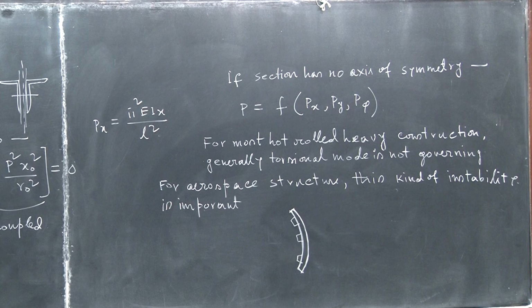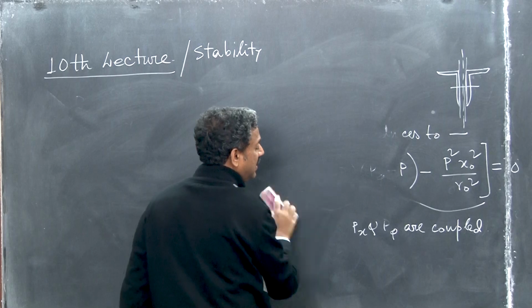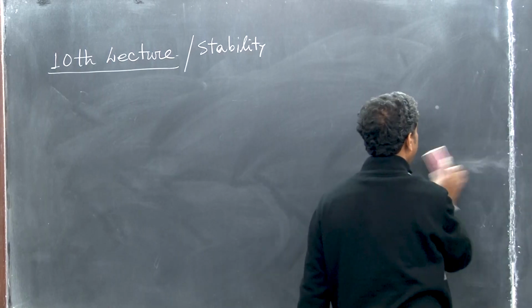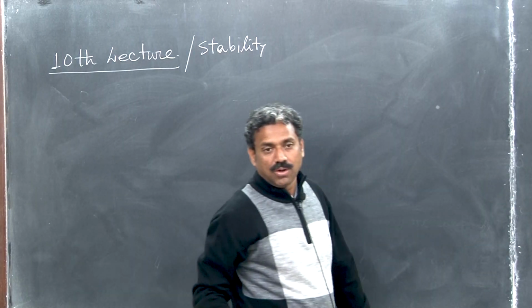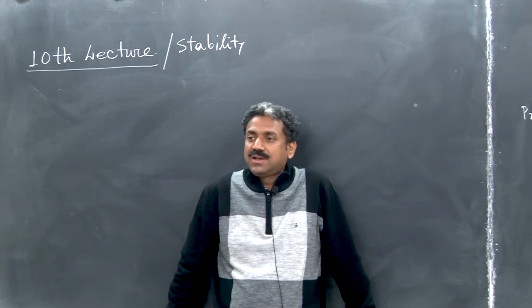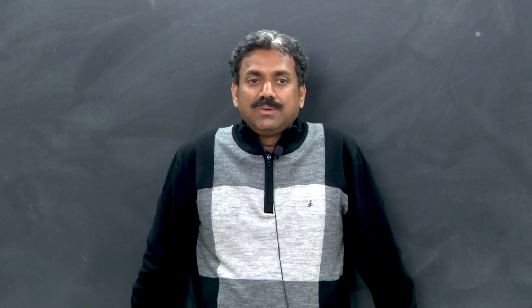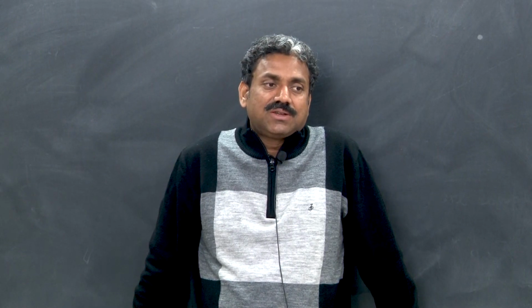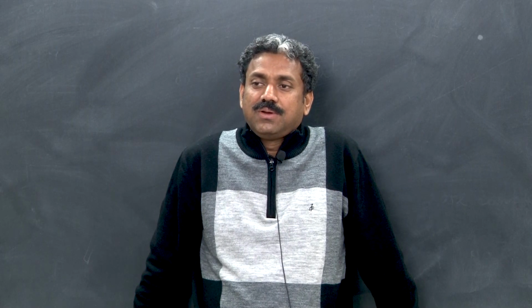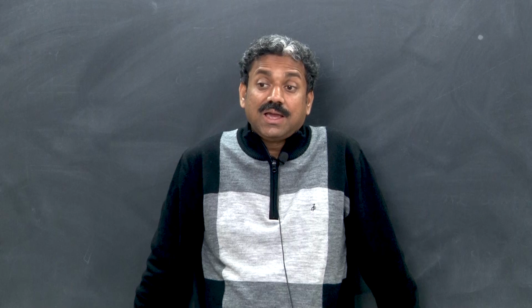So now we have completed torsional flexural buckling, and we have seen that this approach is similar. I don't know whether you are all doing earthquake engineering and have done structural dynamics, right? Torsionally coupled structures. In earthquake engineering this is very important, and there are code provisions for that, IS 1893, for when a building is torsionally asymmetric.